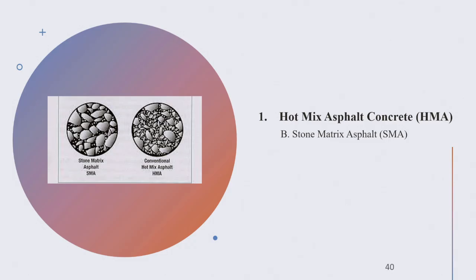As we know, in regular Portland cement concrete, even for rigid pavement, you use coarse aggregate and fine aggregate. Now in roller compacted concrete, you greatly increase the amount of fine aggregate, and you put a cap on the size of the coarse aggregate. So the coarse aggregate is smaller in size and lower in percentage. That is for roller compacted concrete, in order to be able to roll it with the asphalt paver. Because of this, you end up with a mix that really doesn't have the same expansion and contraction as traditional rigid pavement.